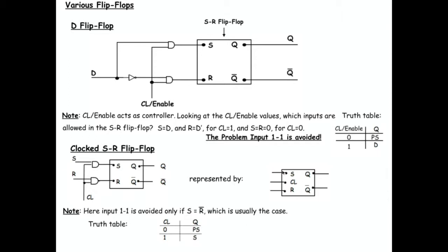So ostensibly, I have 3 inputs, S, clock, and R. And yet, in this truth table, I only have an input of clock. And then here, when I have the function, I have either some kind of previous state, or here I have S. And I tell you that S could be either 1 or 0. So if S were 0, what does it tell us about R?